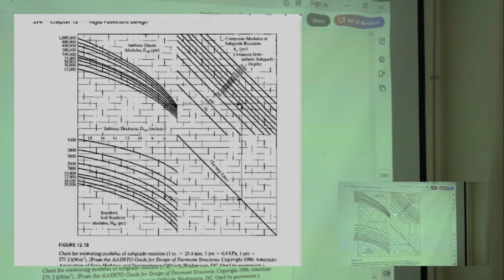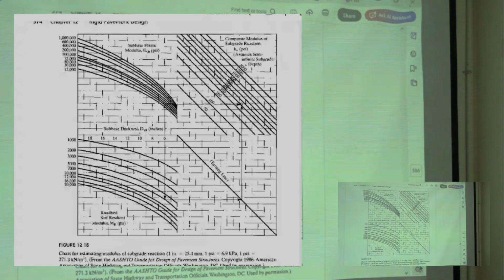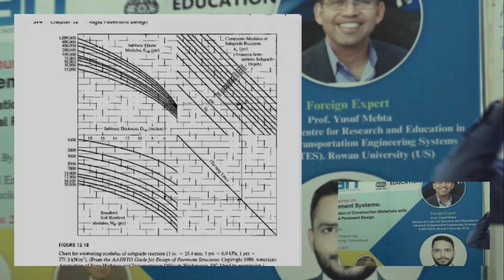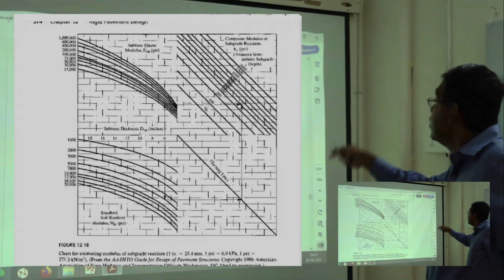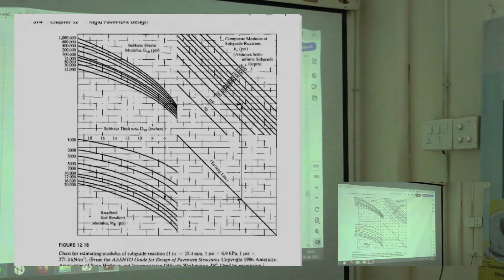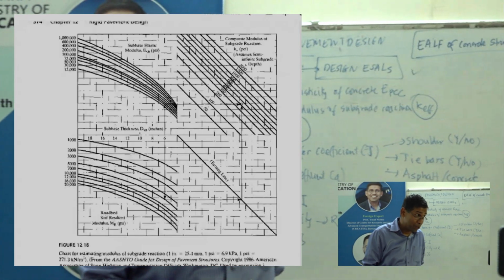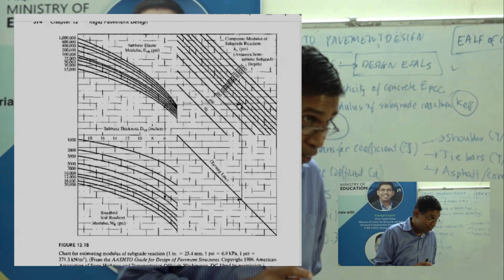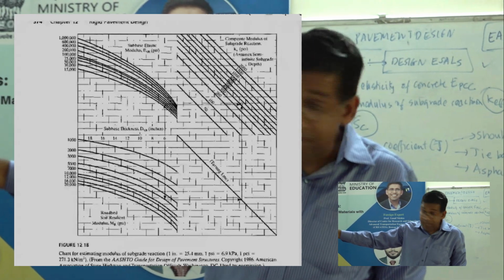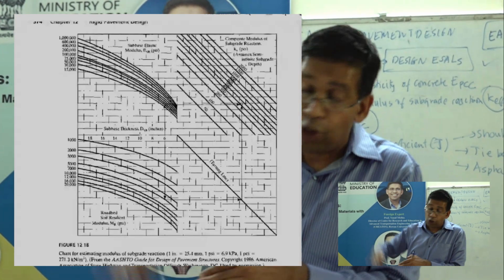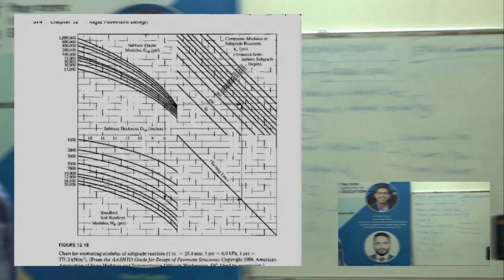And then you go right and come back up on the turning line. Yes. And you get the composite modulus of 300, close to almost 400 PCI for infinite subgrade. For infinite subgrade. You got it? You're not done yet. You've got a couple more steps. That's the first of 3 charts. Okay, that means it accounts for subgrade modulus, thickness of the subbase, subbase modulus, and if that soil was infinite, my starting point is 400. Can I move on? Everybody understood that? Next.